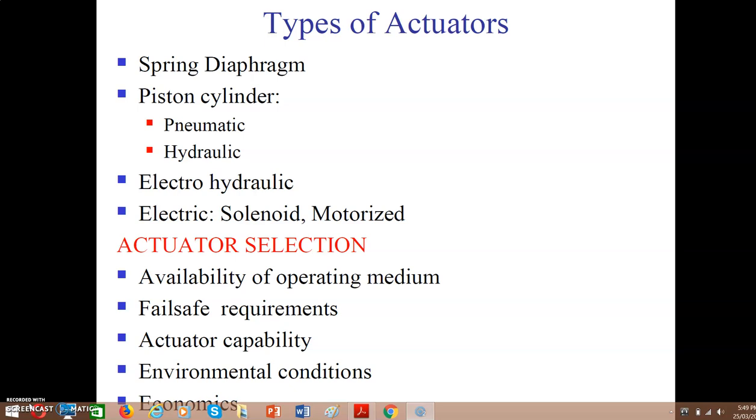In case of rotary valve, the valve opens and closes due to circular or rotary motion of the actuator stem or valve stem. As the liquid passes through rotary valves, it causes pressure drop, and that pressure drop tends to move the valve stem in a circular fashion, but in the opposite direction to the direction in which the actuator is moving it. So that is why rotary valves are not suitable for high pressure drop applications.